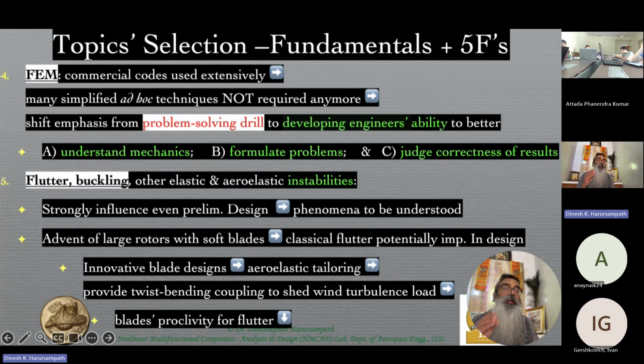But what we are interested in is to ensure that there is some level of stability. And in the beginning classes itself, I will give you a flavor for how this is checked in terms of the material properties. Because for the material choice, remember, we already talked about two important quantitative aspects: the specific strength and specific stiffness. Those two alone are not sufficient. There's a third thing called specific stability, and that's essentially associated with buckling. We will not go through a very rigorous derivation, but we will give a flavor for that so that you are aware of what is actually involved over there, and therefore you can make at least qualitative judgments for the future.